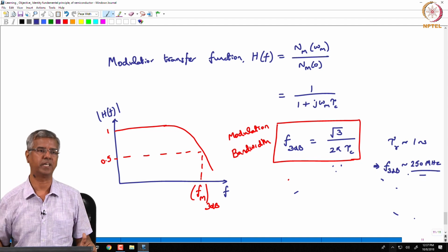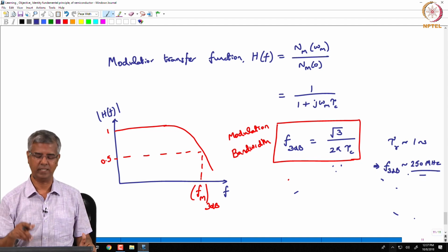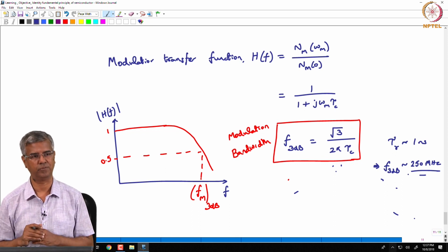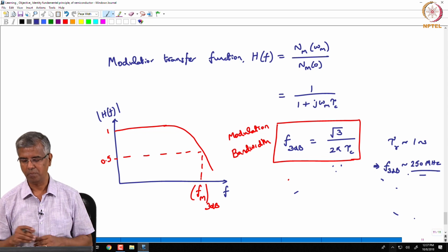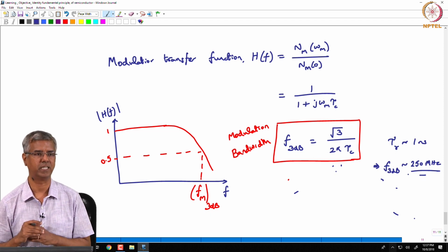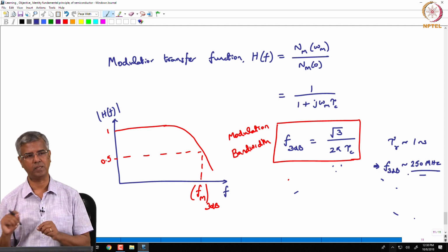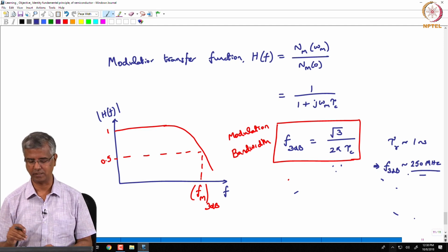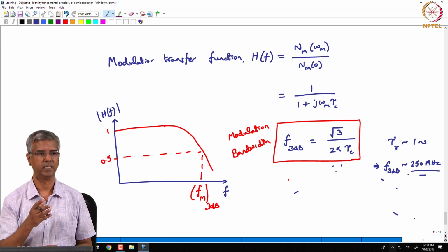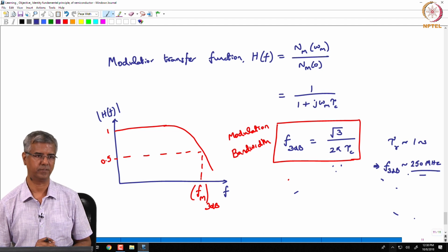It is not a monotonic signature, it starts having some other nonlinearity in it, okay. Then you would have a phase distortion as well happening. But according to the processes that we are tracking here, there is no such nonlinear function coming to the picture. But if there is some other physical effect that is giving you some nonlinearity in the modulation transfer function, then the phase will also get distorted.